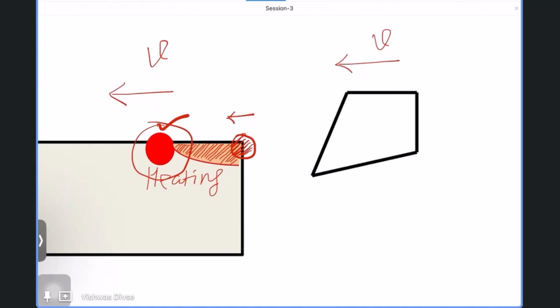And this is very important. Later I will tell you why this depth is important, or now also I will explain a little bit. We will call it the conduction depth. If you don't have sufficient conduction depth, you will not have a sufficient softened layer, so that will not take advantage of laser heating.